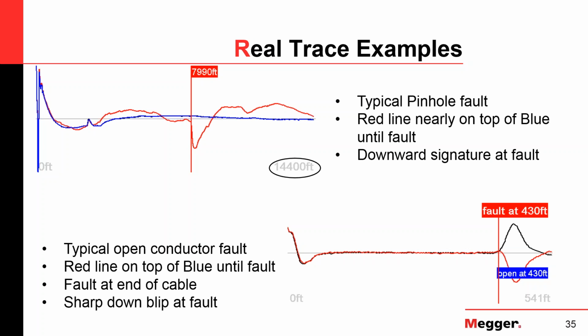Are we referring to the cable velocity here? I don't know. Maybe Henning has to help me for the first time today. Well, I think I agree with you. I would think it has to do with the cable velocity, because it's really the factor that the pulse travels along the cable. Typically, people refer to it as propagation velocity, but I think runtime factor is pretty much the same, because it tells you how long it takes for the pulse to run back and forth on your cable. So I would agree with you. It's cable velocity. I think that's what it's referring to. Okay.